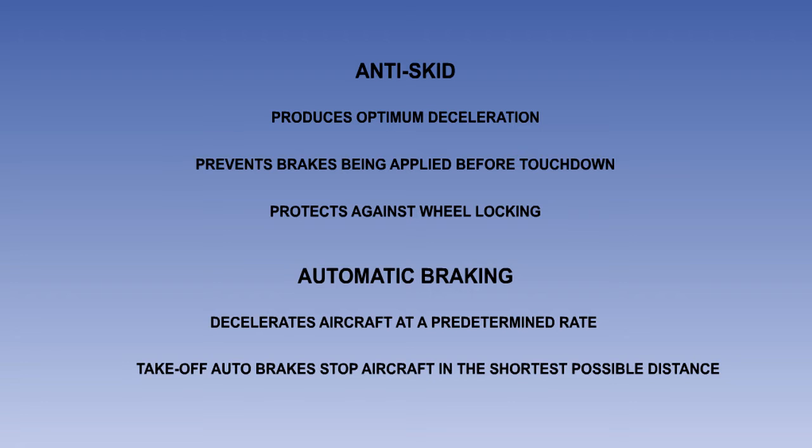The auto brake system, if armed before landing, will automatically apply the brakes after touchdown and decelerate the aircraft at a predetermined rate. If the rejected takeoff mode is armed, in the event of a rejected takeoff, it will stop the aircraft in the shortest possible distance.